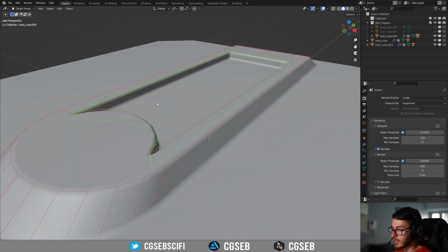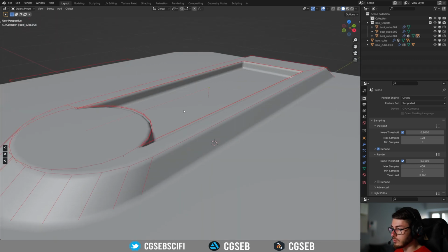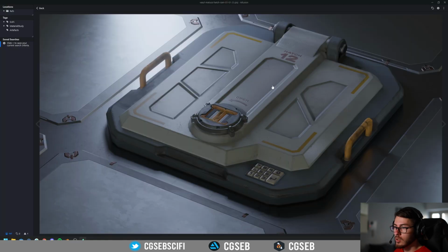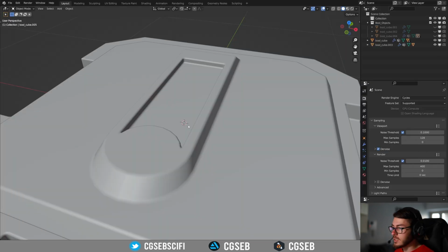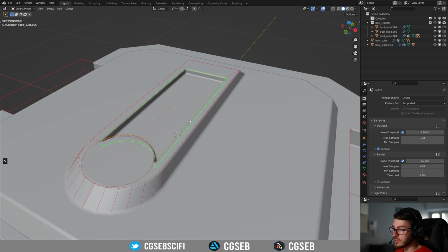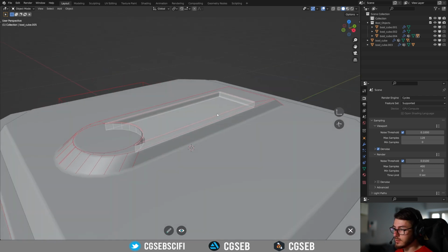We can just right click. So to show the boolean and hide the boolean, you press greater than, lower than, or you can just go here. It does the same. On the example that we have, we also have those chamfered faces from the inside. So to reproduce that, you already know how to make it. We're going to show the Boolean by pressing greater than, lower than. Select this Boolean, press F and go to edit.